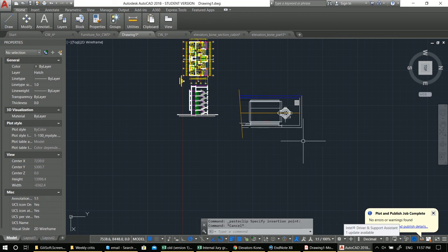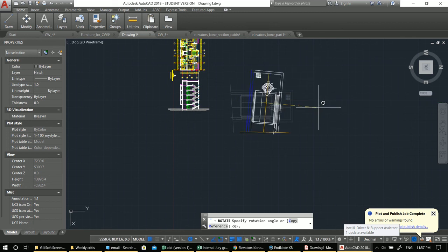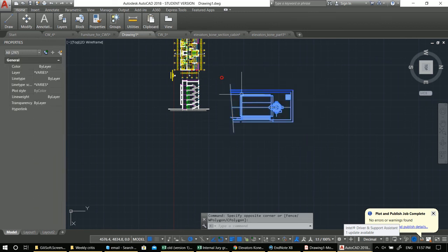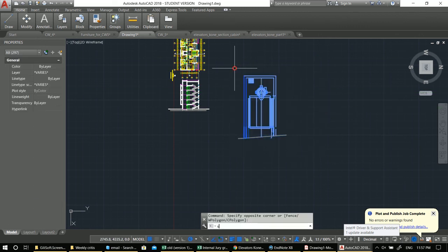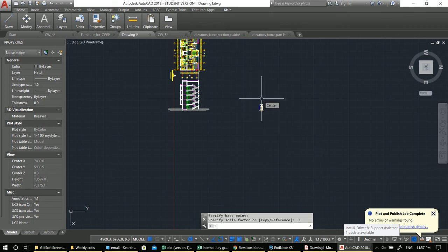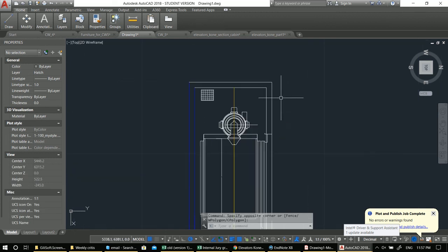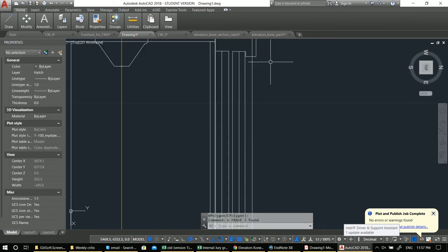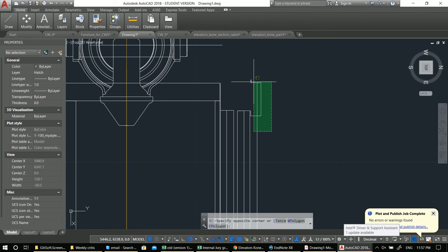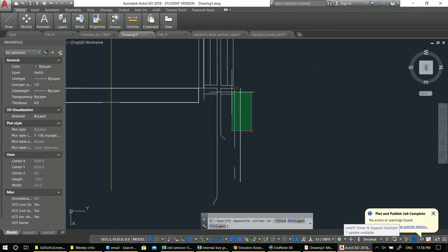As you can see, this one is being drawn in millimeters, although we are drawing in centimeters. So I'm rotating this, RO enter, and then I'm scaling it down 10 times. Let's get rid of these. Let's get rid of these. I already have the walls. I don't want extra walls. I want to see the doors, these doors. So this is the idea. You will find something and you adjust it to your project.